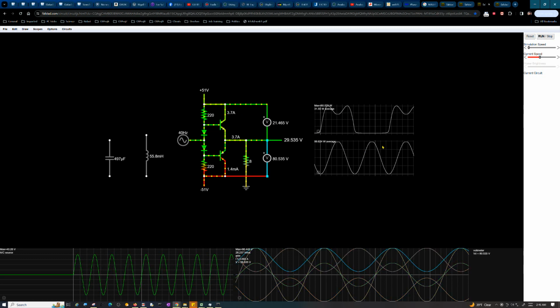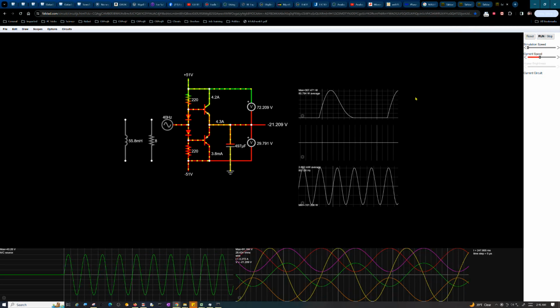But the point is that here it's actually dissipating power on the load, so there's less power for the transistor to dissipate. But over here, in the circuit we were just looking at, there's no power dissipated in the device. It has some energy stored, and then it releases it and throws it back into the system later. So guess what's catching that? The transistor. It has to absorb that power because there's no load absorbing it.